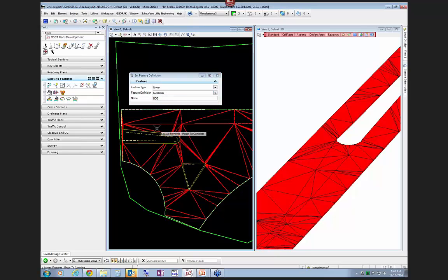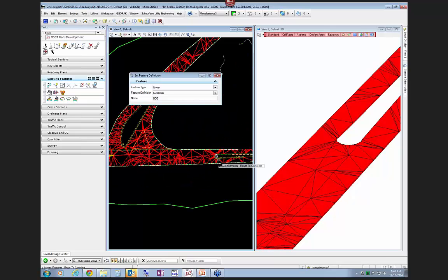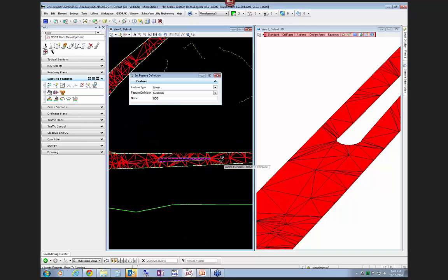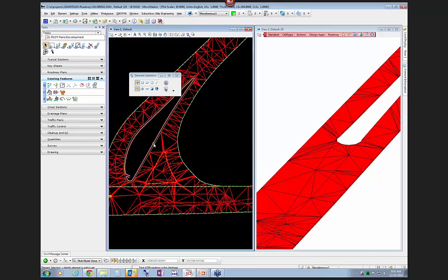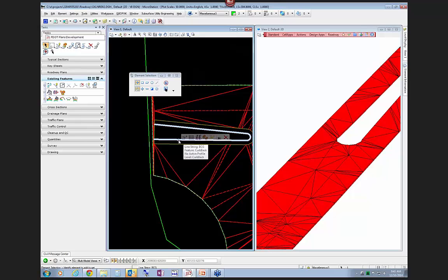and in the curb and gutter, there is a curb back linear style. In order to do that, you can select the elements individually, or you could have done them by level. Since we only have 4 of them, I'll go ahead and select them individually, provided that you've got clean topo line work. And then reset, and it now makes them civil back existing features, or curb back existing features.